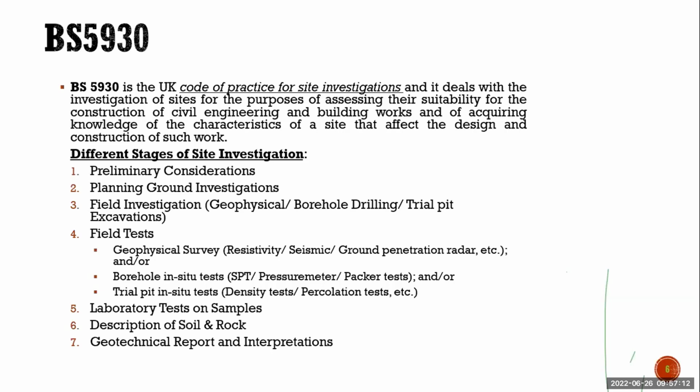Now party B thinks the soil is not that stiff. Even if it is stiff, if I use a 50 kg hammer, it will take many blows, and if it takes many blows, it means the soil is stiff. So in my perspective, it's the right approach. But in the end, they will not speak the same language, because if party B uses the 50 kg hammer, the penetration will take longer than with 63.5 kg.